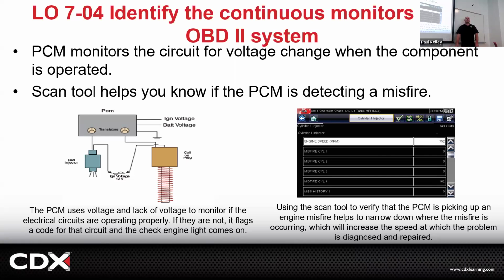I don't always do this, but this was when I wasn't that busy. I went out and I said, I've got a code, P0171 fuel trim lean. What part do I replace? I just waited. No response. Because when you get a code like that, fuel trim lean, there's no sensor, there's no part, there's nothing listed.